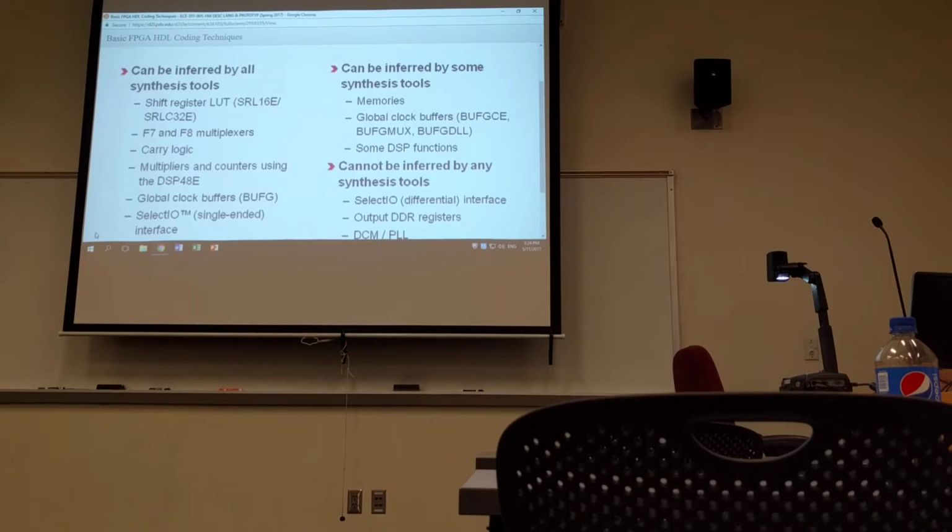There would also be no warning or error message sent by the synthesis tool, since the tool would think you wanted to build a shift register with your standard flip-flops. There would be no error in that. Likewise, the implementation tools would not give a warning or error message, since the netlist made by the synthesis tool would reference flip-flops. And as we know, there's nothing wrong with that.